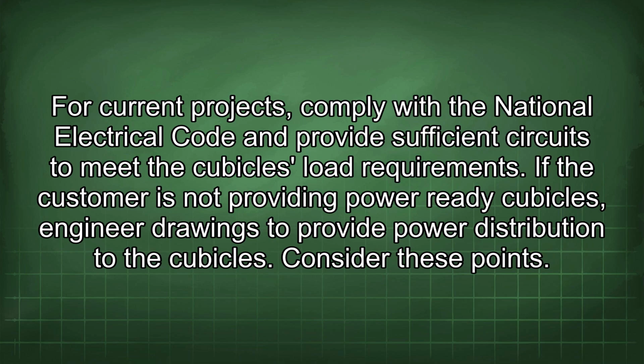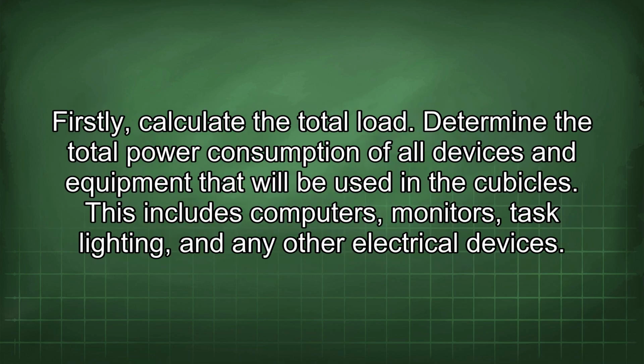For current projects, comply with the National Electrical Code and provide sufficient circuits to meet the cubicle's load requirements. If the customer is not providing power-ready cubicles, engineer drawings to provide power distribution to the cubicles. Consider these points. Firstly, calculate the total load.